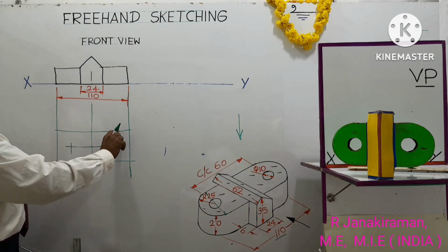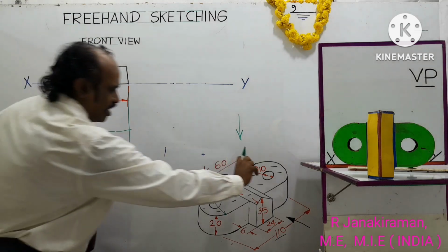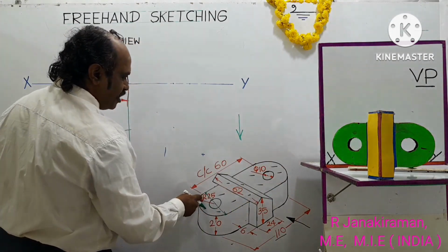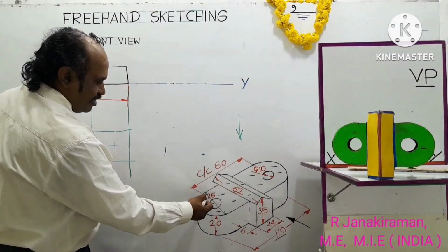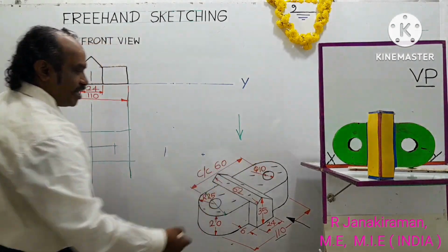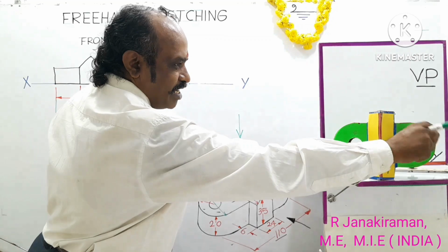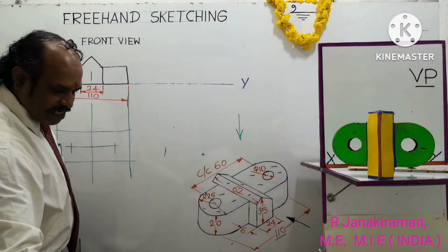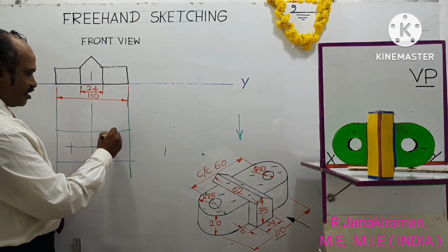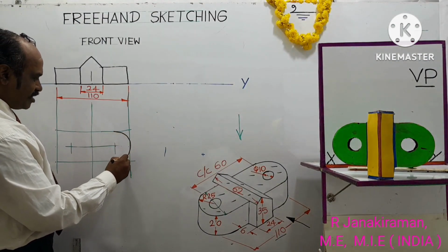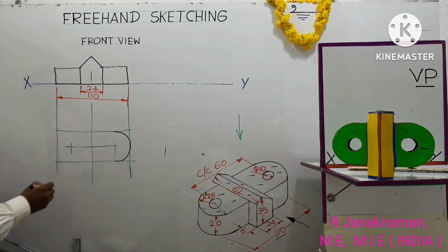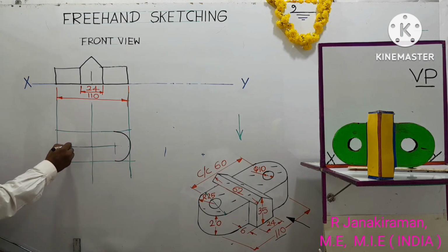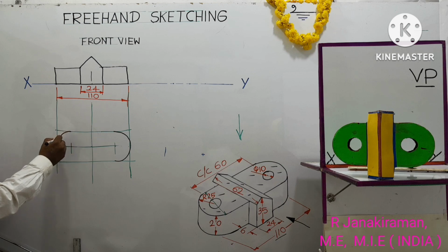So with this center, the radius of this right side arc is given as 25 mm. Only one side has this dimension; the same can be taken for the other side also, radius. Now I'm going to draw this radius, seen in the top view, shown green in color. With this center as a reference, draw an arc, a semicircle, with 25 mm as radius. Similarly on the left side, with the same center as reference, draw one radial semicircle, so that this will be the radius. Okay.